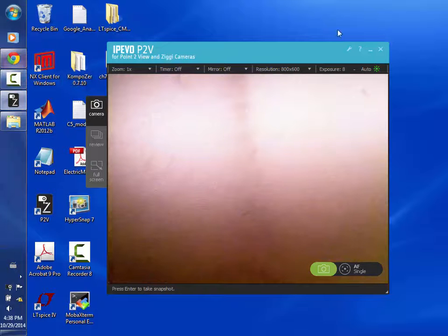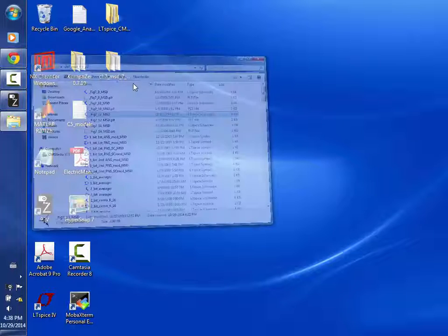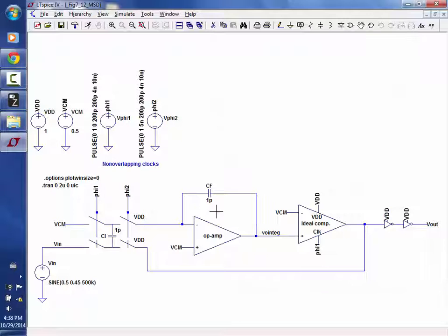How do we select that gain? Okay, well, let me ask this. What do I want here for this integrator output to be? Yeah, as big as possible, but below VDD and above ground, right? I want it as big as possible because, as we'll see, it reduces the noise, but it minimizes the stress on the comparator. But I don't want it so big that the bucket overfills and the charge spills out. Does everybody follow that?